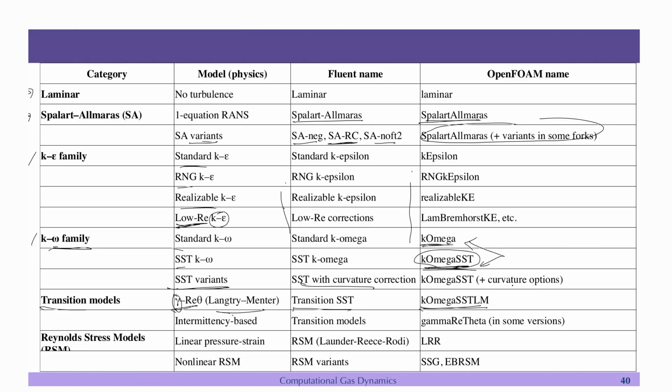So, there are actually two different versions of OpenFOAM, one goes as v2306, v2312, and there is v9, v10, v11 and so on and so forth. So, there are different names for the files, that is very similar, but names are different. Okay. So, there are the intermittency based models, there are actually more transition models which are not mentioned in this table. You have the laminar kinetic energy model, and then you have some variation of the SA model, SA BCM model and so on and so forth.